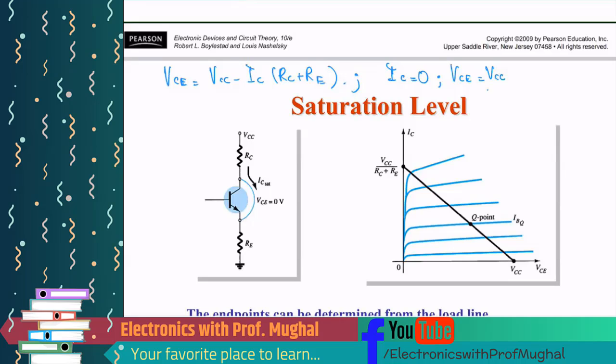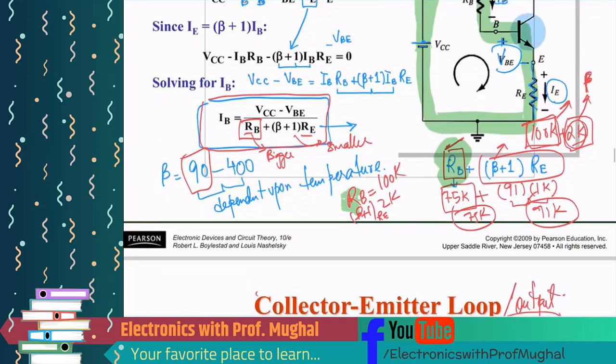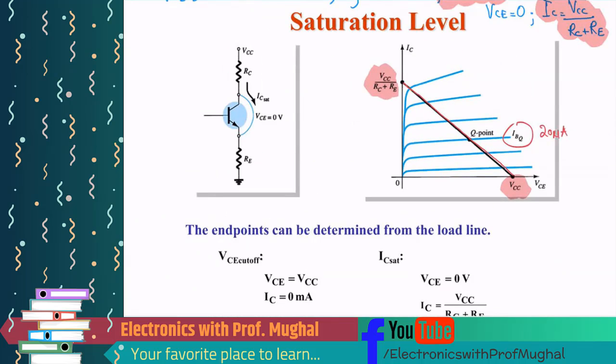And the second time we put VCE equal to 0, which gets us IC equals VCC over RC plus RE. These two equations, VCE equals VCC and IC equals VCC over RC plus RE, that's what we get over here, and that's what we got over here. And then based on that, we create a load line. This IBQ, how do we calculate it using this equation? We get IBQ, whatever that number is, say that number is 20 microamps. Wherever this load line intersects that IB, that will be your Q point.